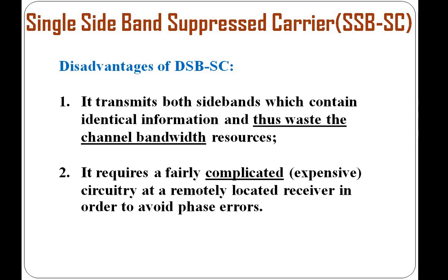The phase shift will be plus or minus 90 degrees, depending upon your frequencies. If you have positive frequencies, you get minus 90 degrees of phase shift. If you have negative frequency components, then you go for plus 90 degrees of phase shift.